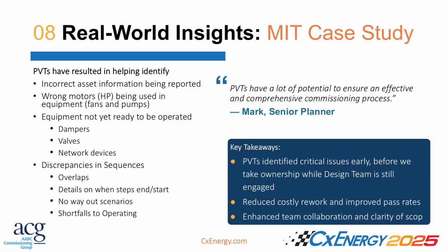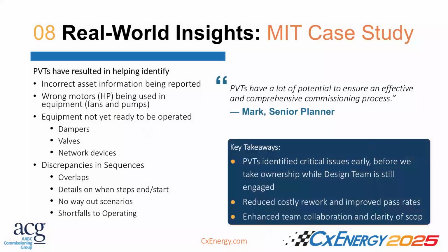All right, you want to talk about real life? Yeah, so real life, again, we found motors that weren't the right sizes and pump impellers that weren't cut right, things like that. So it's a lot better to know that earlier than later. There's not a lot you can do when you're moving in except run the redundant pump or the redundant fan to try and overcome that till you get the right equipment. And then you've got to put in for a shutdown and wait for that. And nobody wants to start a project or end a project that way.